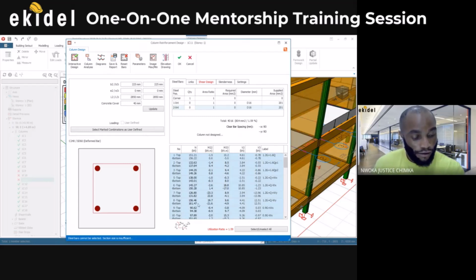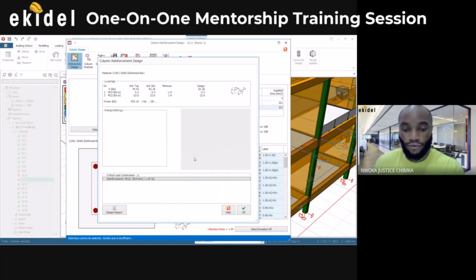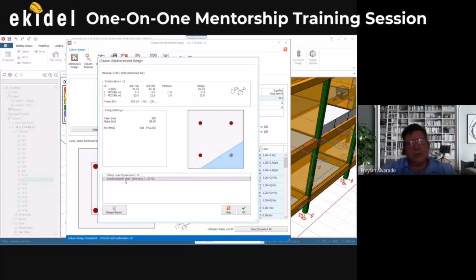Can you hear me? Yes. Okay. So to increase the section size, you need to come here. Let's say 250 by 250, then design again. You can see now it's showing us the bar. If it's not okay, you won't see this bar here. It will not show the reinforcement.